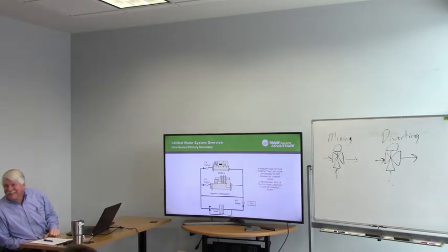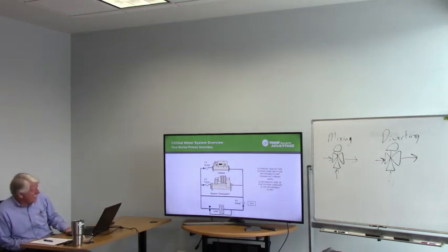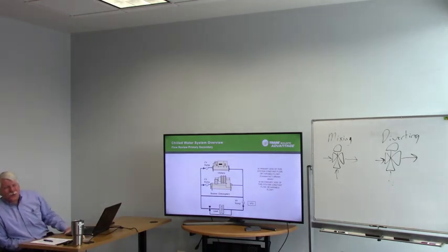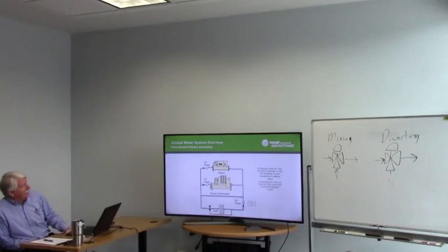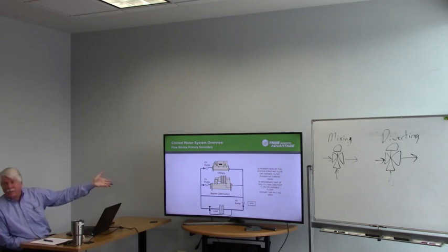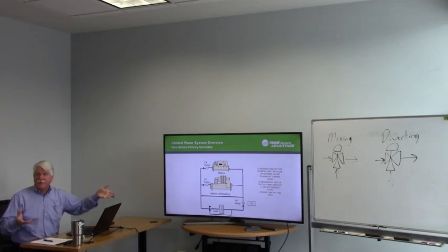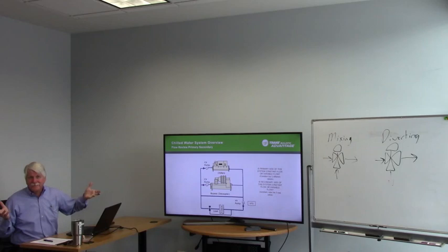I got Travis's head in my way. He was hiding the bypass on the coil. Okay. I added a three-way valve down there to make that a trick question. That's really constant flow because, again, there's a three-way valve. So, we got a VFD out there. Is the VFD gonna do anything? No, it's gonna sit there at constant speed all the time because it's a constant flow system.